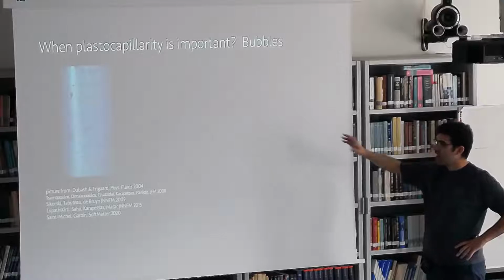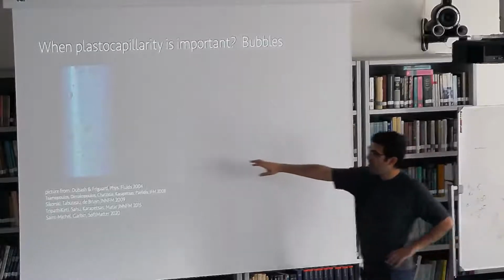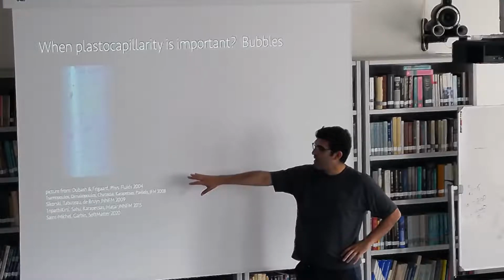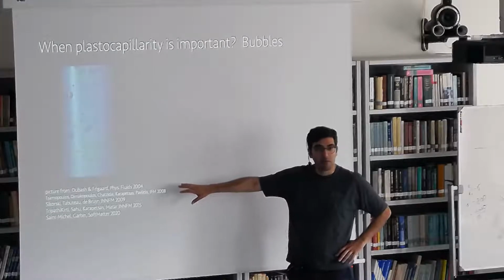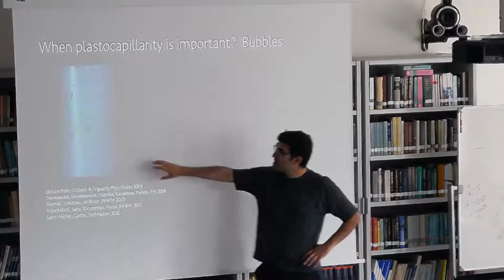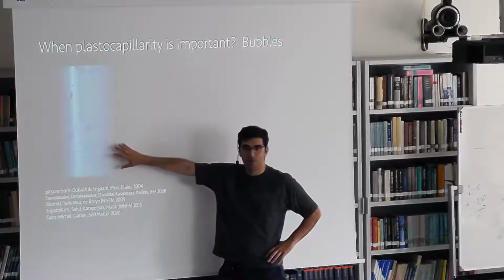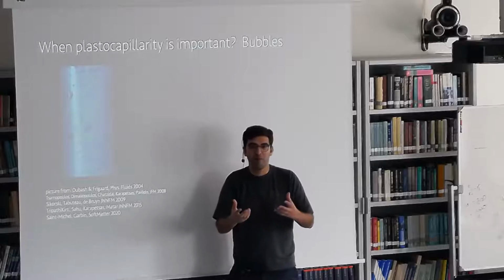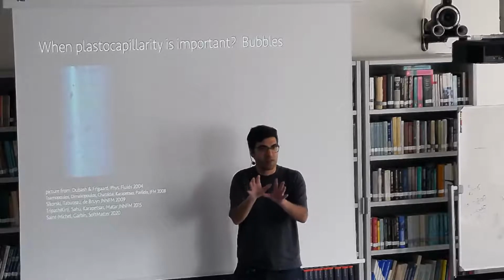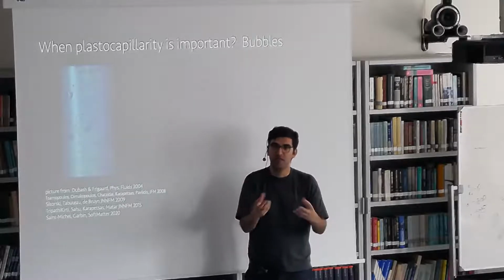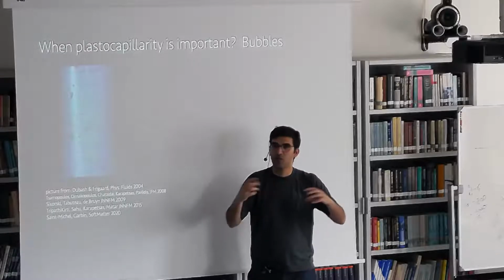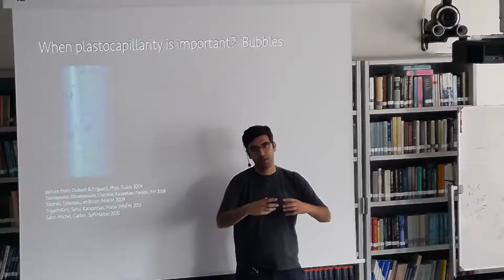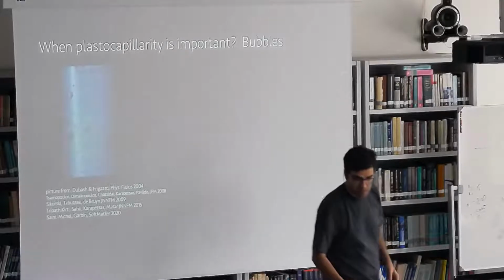And there's another category of bubbles. I took this work from the group of Ian Frigaard at UBC, which has extensively worked on bubble dynamics in viscoplastic fluids. This is a static picture, so this is a steady state. You can look at hair gel or mayo, and you can always see these bubbles that are static there. The reason that you can get these different, non-unique shapes of bubbles is, again, the yield stress. Surface tension wants to keep the bubble spherical, but the yield stress doesn't allow it.